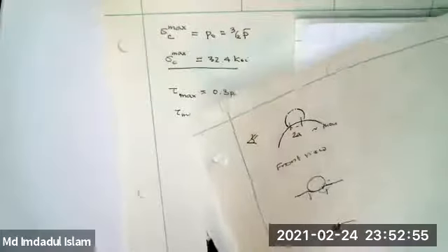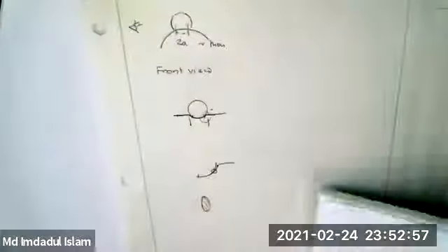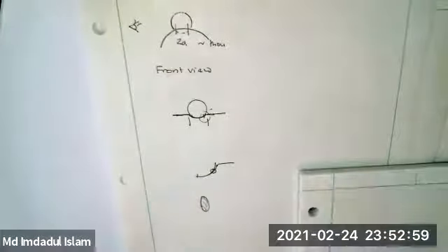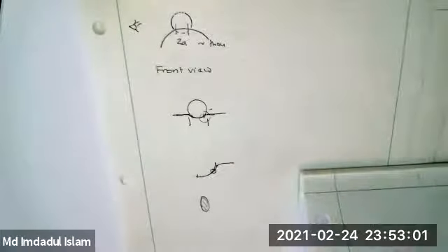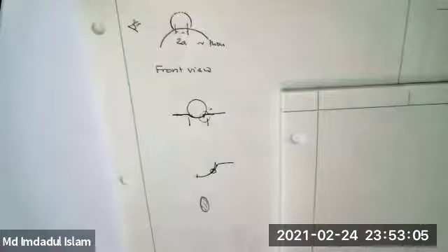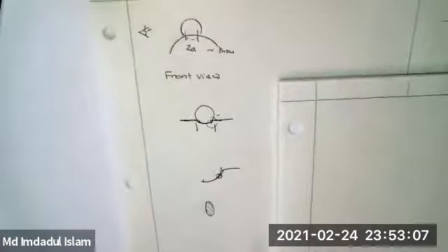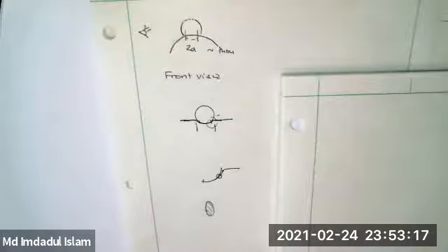Right, we're going to switch topics. Contact problems are important to see because they introduce some new physics. If you get comfortable with that, you get comfortable with the idea that you can have pressures in contact that exceed the yield strength and not have yielding. On the other hand, with a lot of these contact problems, the loads are cyclic, and so fatigue is a problem. And relatively light loads produce relatively large stresses because the contact regions are small.